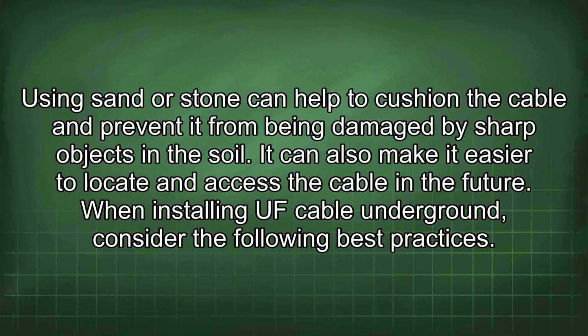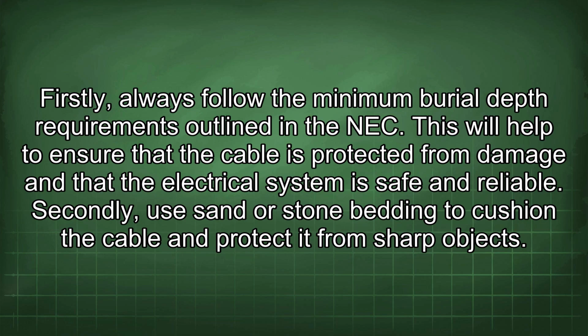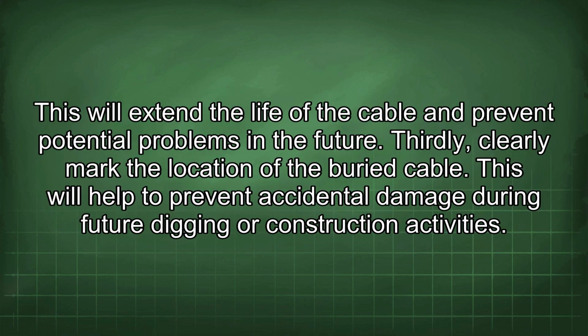When installing UF cable underground, consider the following best practices. Firstly, always follow the minimum burial depth requirements outlined in the NEC. This will help to ensure that the cable is protected from damage and that the electrical system is safe and reliable. Secondly, use sand or stone bedding to cushion the cable and protect it from sharp objects. This will extend the life of the cable and prevent potential problems in the future.